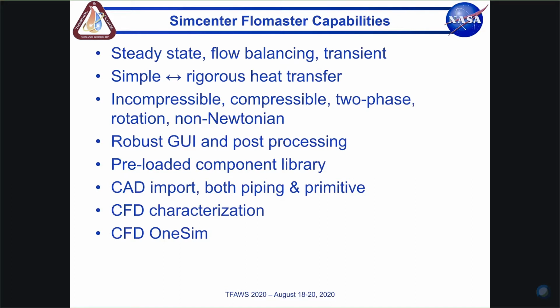So just going over some broad capabilities of SimCenter Flowmaster. We are a tool that works in the steady state and the transient time domain. So you can do quick steady state analysis to do pressure, temperature, flow prediction. You can do full on transient for temperature propagation, flow propagation, but also things like fast transient behavior like water hammer and surge cavitation.